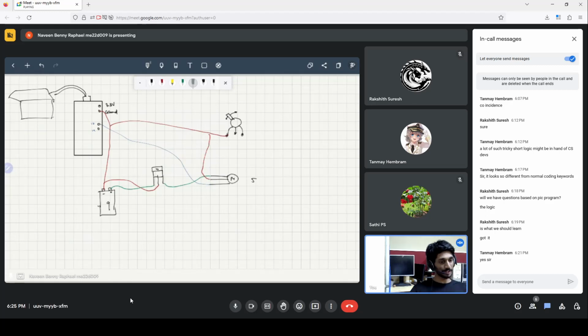So the potentiometer, in the case of ESP32, the input analog values have to be between 0 and 3.3. The potentiometer will give values between 0 and whatever the high voltage is. The high voltage therefore has to be 3.3. So I take the 3.3 and connect it to the high of the potentiometer.